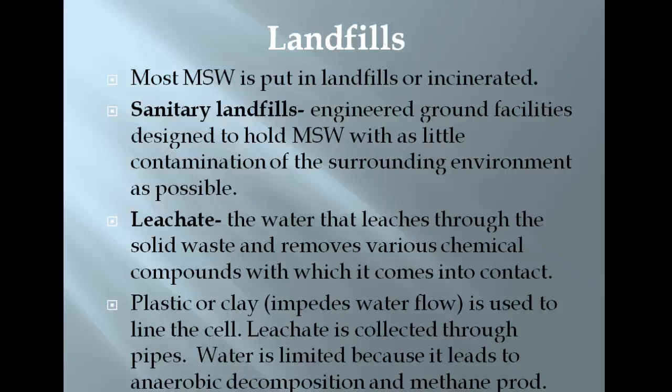So you want to line the cell. Remember, I told you that they dig these giant holes, and you have to take into account the geography of the land, the type of soil that's there, the topography that would be ideal to have a landfill. So they'll dig a hole or a cell, and then they line it with plastic or clay or both. And clay is a sedimentary rock. You've seen it before, even like modeling clay, where the grains are so tiny, and when they're packed together, they don't let water get through. So it's impermeable, and that's why they want to use it. Impermeable means water won't go through.